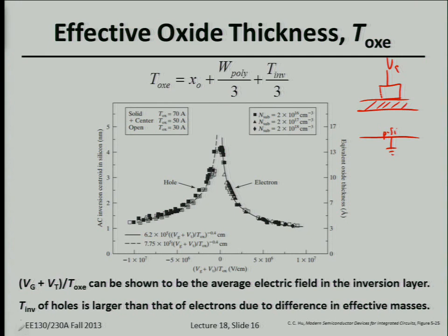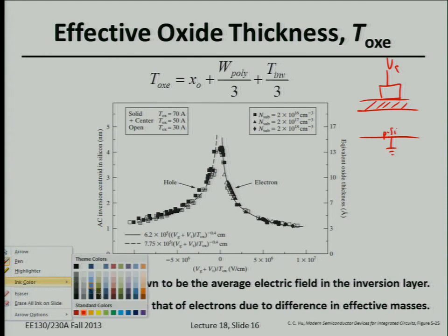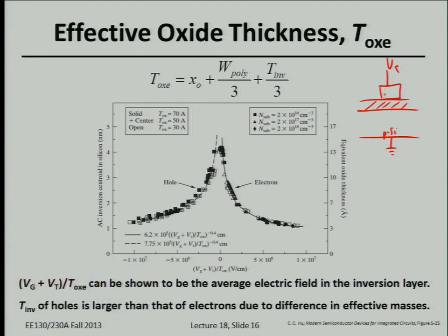So if you add positive charge, let's say we increase the gate voltage by a little bit, so we're adding a little bit of positive charge here. In inversion, we always were saying we're adding electrons at the oxide interface, right? So there's some depletion width and some depletion charge. But once we have a gate voltage beyond the threshold, we're adding electrons right at the interface. So the small signal capacitance is just going to be equal to the oxide capacitance because we're adding charge at both interfaces of the oxide.